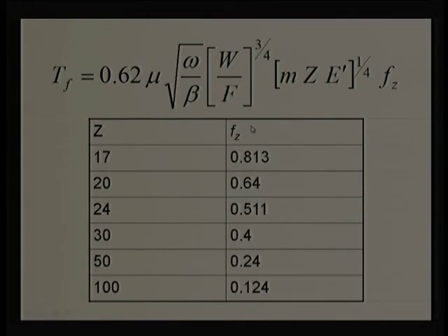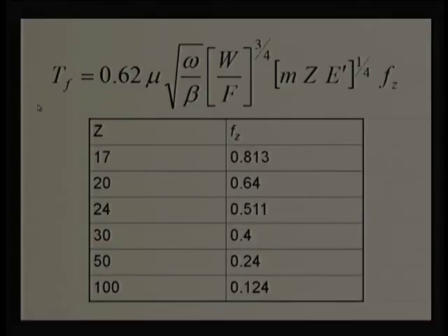So, when we talk about gear design, it will not be simple like this. It will be based on combinations of number of teeth, Young's modulus, effective curvature, load, and speed parameters. So, there is no one-way rule that we need to have only these parameters. It is always a trade-off, always a combination, and its overall package gives a lower or a higher coefficient of friction, and we know if the temperature is higher, viscosity is going to decrease, and the viscosity decrease is going to decrease the load carrying capacity. So, it is basically an iterative scheme.